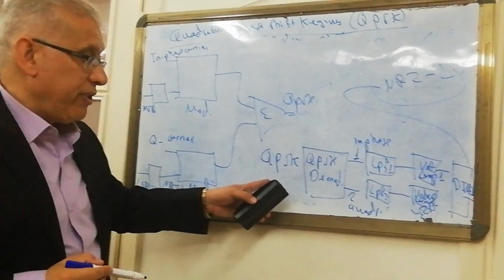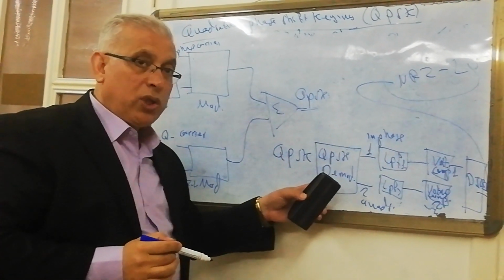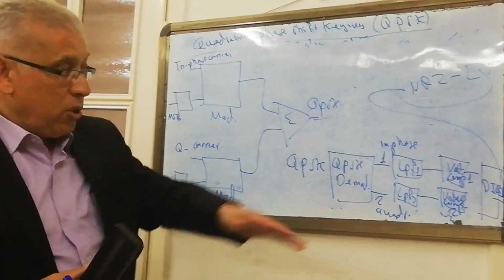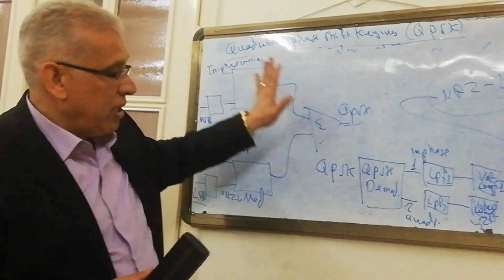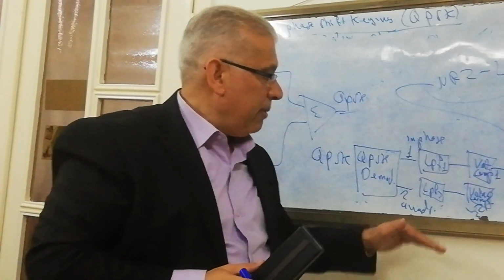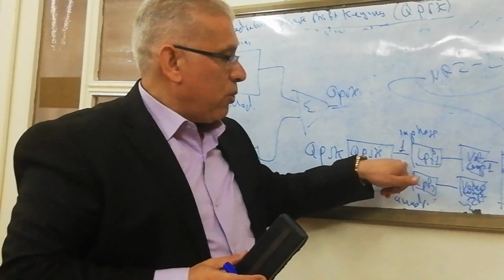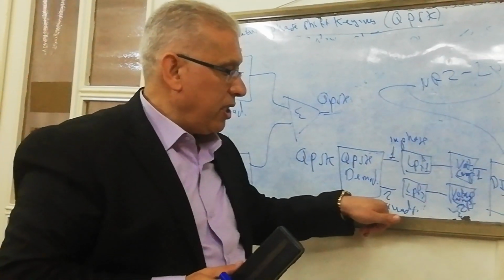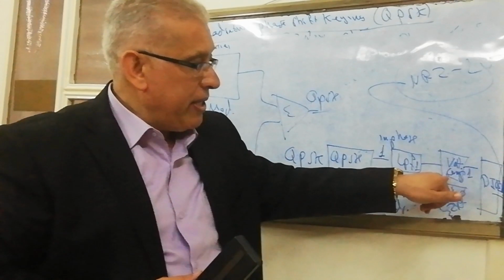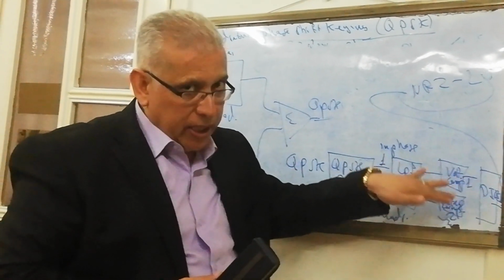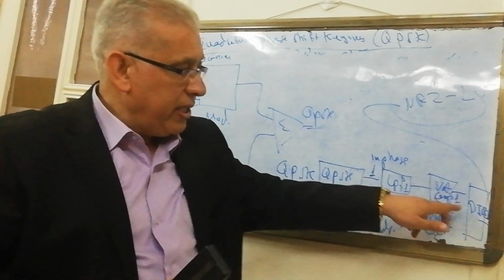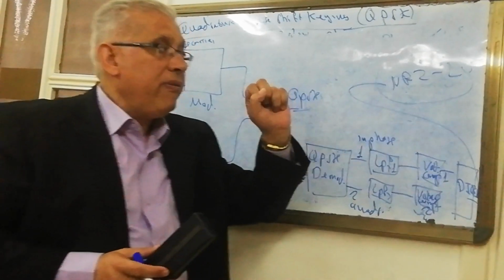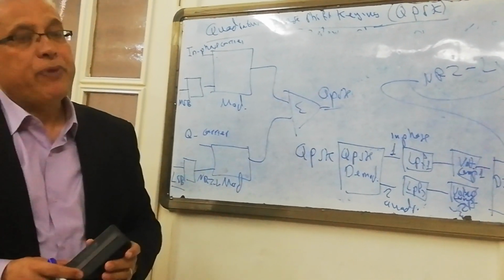So the quadrature phase shift keying waveform is applied to the quadrature phase shift keying demodulator. The output will contain the remnants of the carrier. So here we'll have two channels because we're talking about the in phase channel and the quadrature channel, 90-degree phase shift between them. First one, we have the low pass filter number one for the in phase channel, which removes the carrier components. Low pass filter 2 for the quadrature channel to remove the carrier component, the remnants. Squaring up the signal, we use voltage comparator. That's typical as we used in the previous phase shift keying, and differential encoding in order to have the non-return to zero L or level output, which is the data stream which we transmitted.